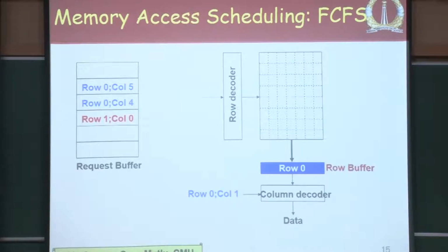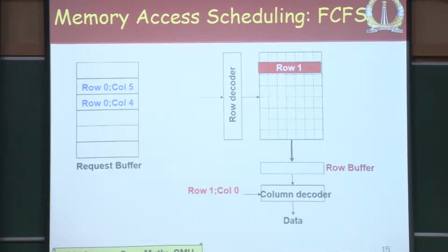Therefore, the memory controller which is doing the access order scheduling, in the case of a simple FCFS, would schedule this request because this has come earlier, and therefore, would incur an additional row buffer miss for this particular thing. Whereas, a smarter memory controller would reorder these requests and send those two requests earlier, and therefore, avoid that particular row buffer miss. So, what is it that we gain because of that? Those accesses will not incur an activate and a precharge, and therefore, they could be done with only 10 cycles rather than 30 cycles. So, that is really what I wanted to get into.